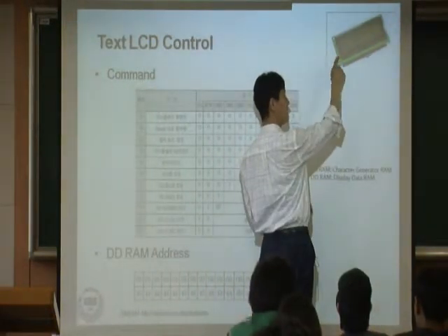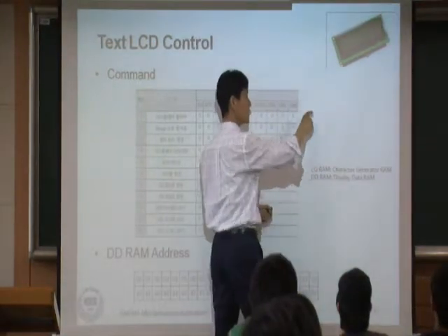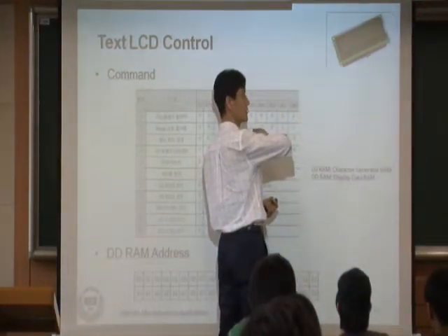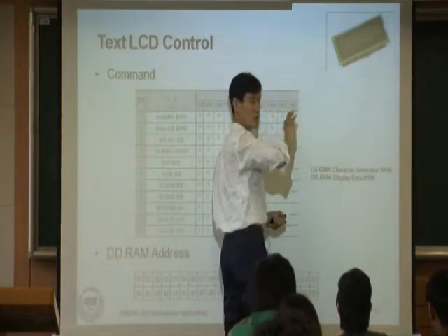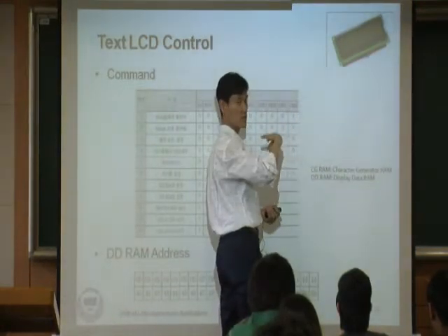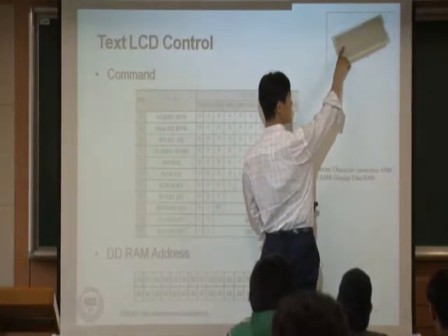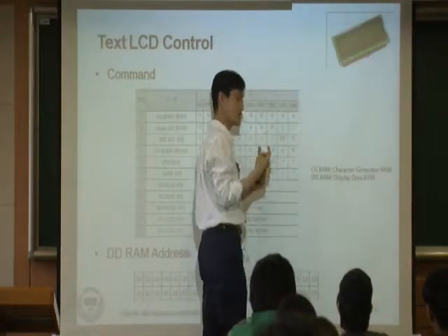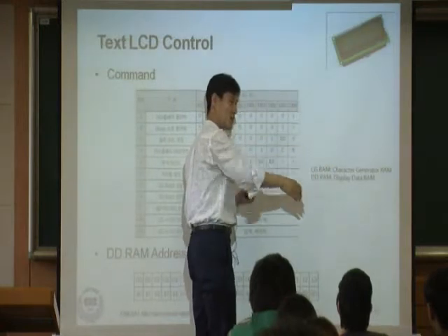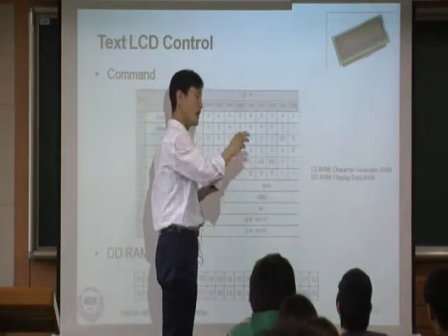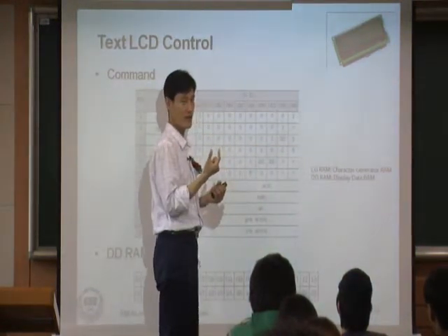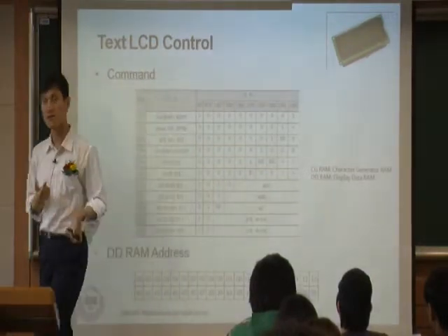But anyway, for every LCD device, you cannot transmit these letters right after one another, immediately. What you need to do is write one value and wait a certain delay, and then write the next one, wait a certain delay. Every time you do, you need a delay. And that delay is actually pretty big.